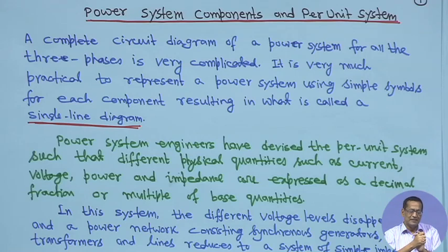Another thing is that if the system is unbalanced, then you have to consider the mutual coupling between the conductors as well as between the conductor and the neutral. I mean, between the phases you have to consider all the mutual phase conductors as well as phase to neutral conductors, the mutual inductance, if the system is unbalanced. Particularly for the transmission line, each phase is carrying almost the same power.